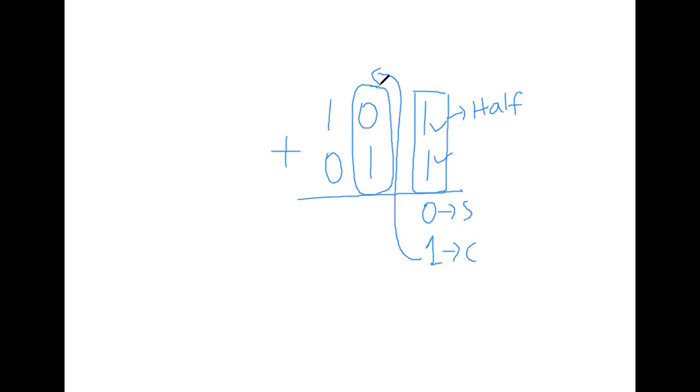That's why the binary adder can be designed by using full adders only. We'll use full adders to design a binary adder. Why full adder? Because in full adder we have a provision to add the carry bit. That's why half adder cannot be used to design the binary adder. Only full adders can be used. So that is the difference between half and full adder.